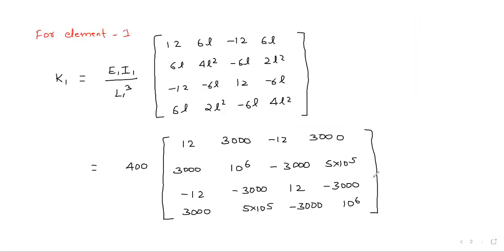So we can write the displacements here. This will be for V1, then theta 1, node 1, node 2, V2 theta 2. This I am talking about rows, right? Similarly, we can write here, this column belongs to V1, this column will belong to theta 1, this will be for V2, and this will be for theta 2. This is talking about these columns. I am just marking these things so that when we calculate the global stiffness matrix, it will be easy for us, right?